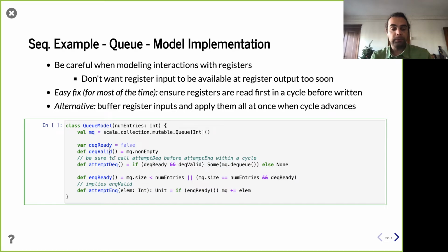And so one of the challenges that comes up when designing these kinds of components, especially with sequential components, is how do you model registers, right? Because when you write programs, you're very used to writing things sequentially and the update order is in that sequence. Hardware, of course, updates happen simultaneously. And so sometimes those semantics aren't well captured by a program if you're not careful. Now, as a veteran programmer, you're probably not realizing you're doing this consciously, but you're probably very adept at ordering statements in a way that makes sense. And we just need to do the same thing when doing hardware.